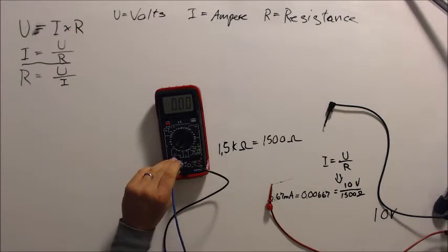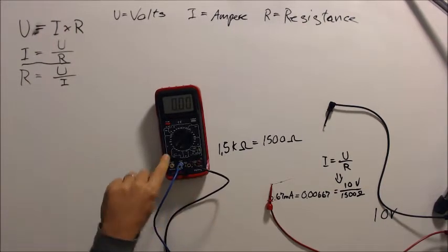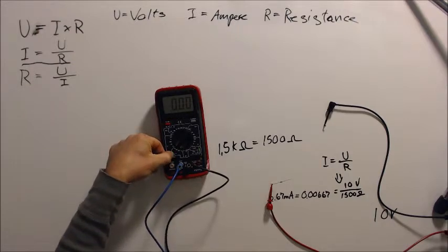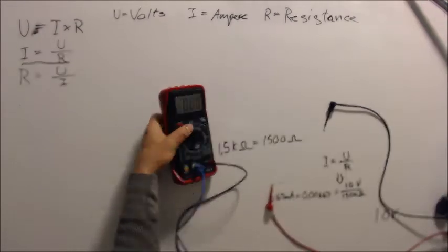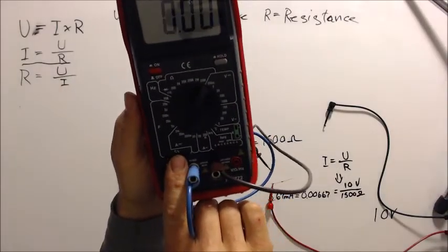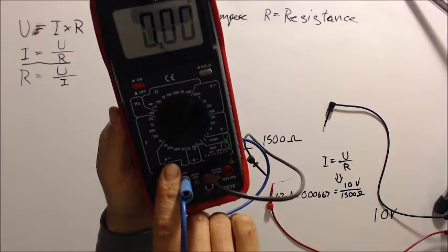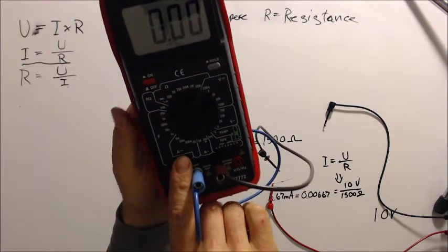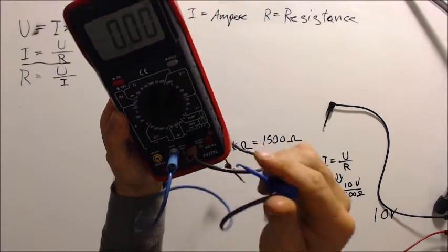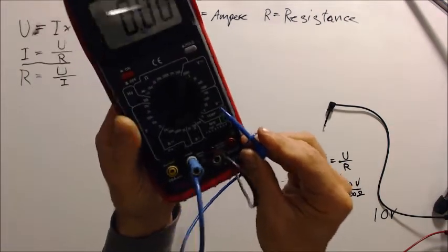So we expect to find a small size, so we're in milliamps, and it says here milliamps. This symbol down here, the section that we're putting it in, is showing these dashes here, and that means that it's DC. So we are going to need that piece of information for this measurement. AC is this sinus curve here.